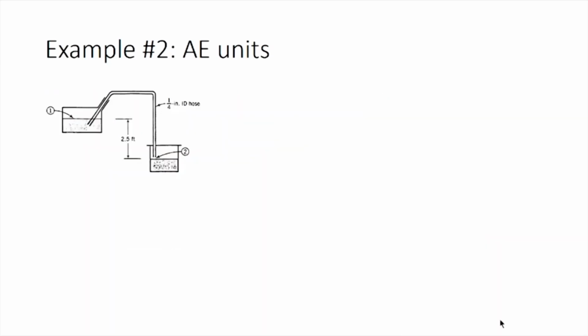The general mechanical energy balance would be delta P divided by rho plus delta u squared by 2 plus g delta Z plus F cap equals minus Ws dot divided by m dot. Here we have been told that the pressure at point 1 and point 2 are both 1 atmosphere, which means delta P would be equal to 0. We also do not have any moving parts in this system, which means shaft work will be equal to 0.